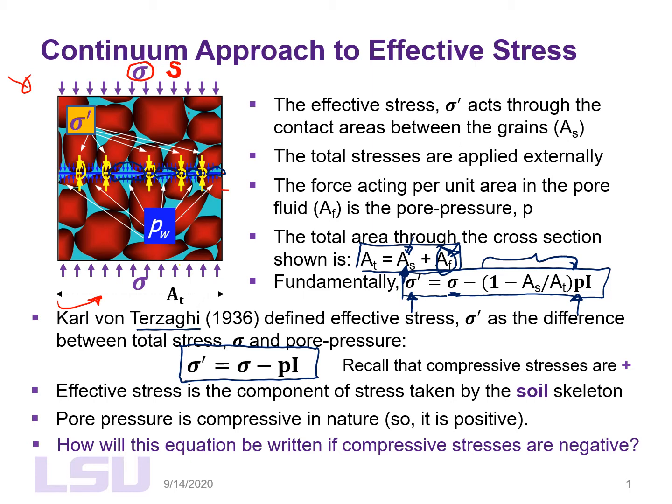It's just saying that total stress equals effective stress plus pore pressure. Why do we have this identity matrix? Because these are tensors. Pressure by itself is a scalar, so we multiply it by the identity matrix like I had explained before. 1, 1, 1, everything else is 0, so that you have pressure along the diagonals.